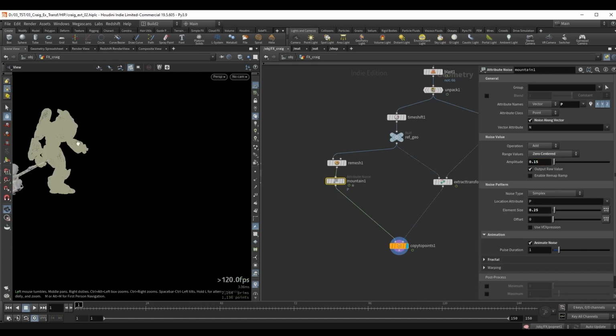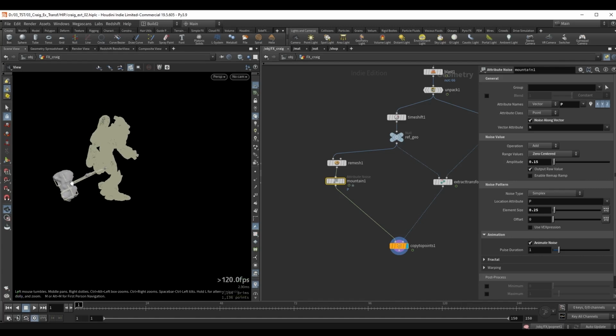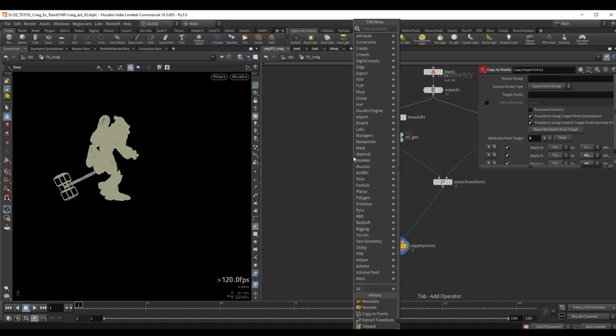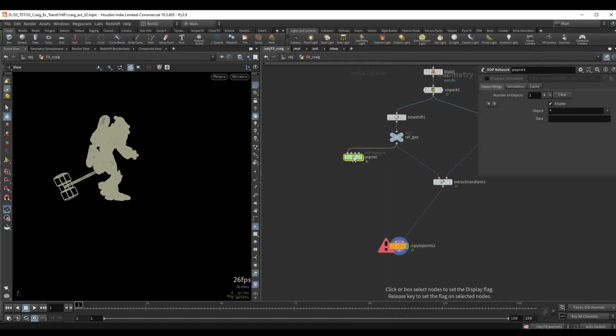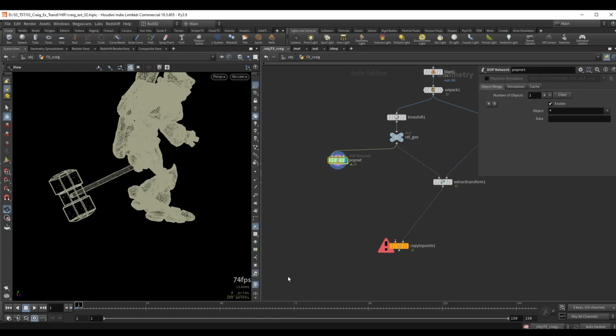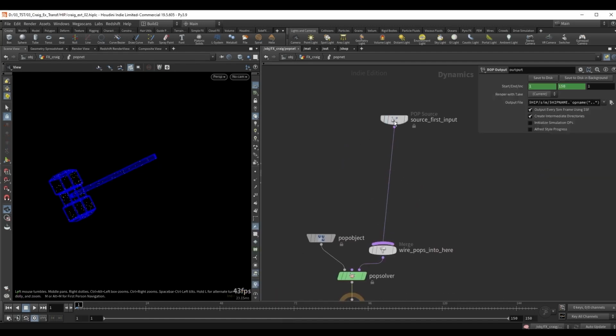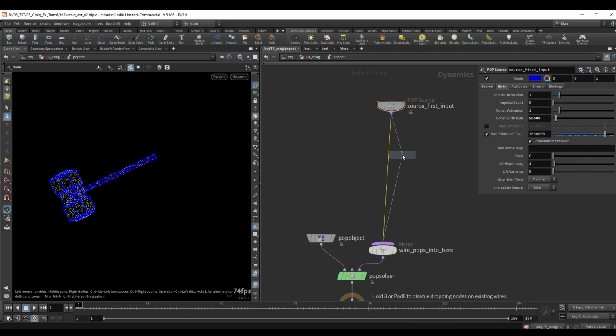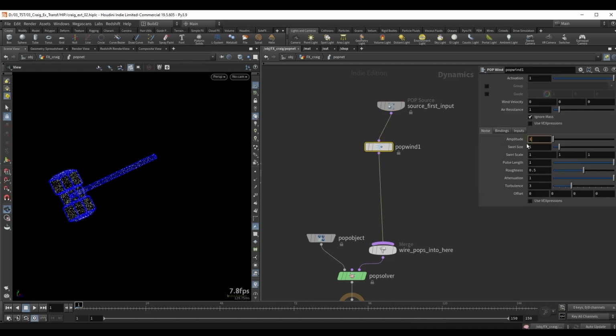And to give you just one more example, if you were to have particles that run over this hammer and you want to stick those particles to the hammer, let's go ahead and, from this reference geometry, drop this inside a popnet. And let's switch our display back to pixels. Let's step inside and let's just increase the count. So in the birth tab, let's maybe add another 0 here, and let's decrease their life to maybe a value of 2. And let's move them by using a pop wind, and I will increase the amplitude here to 1.